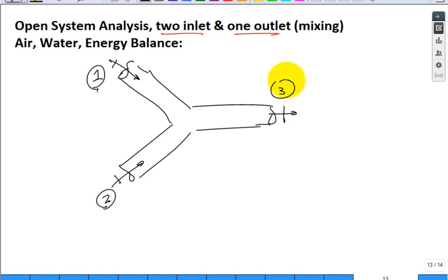If you just have mixing, a lot of times Q dot is equal to 0. There's no heat transfer, no cooling. There's no m dot liquid removed or vapor added. You're not humidifying or dehumidifying. You're just mixing two moist air streams.